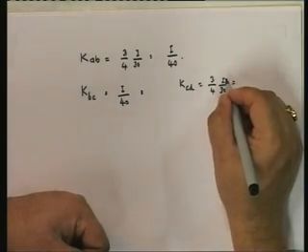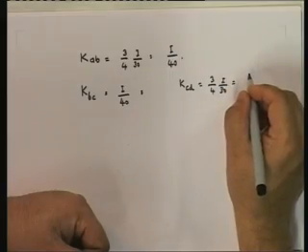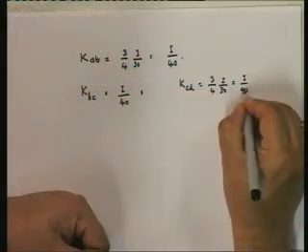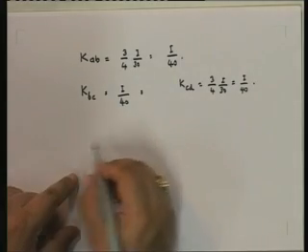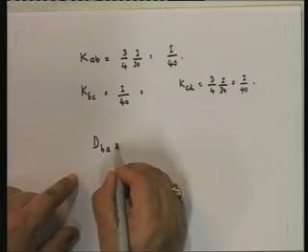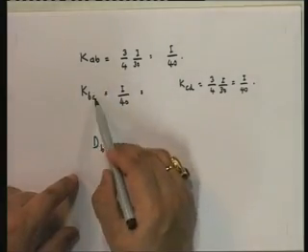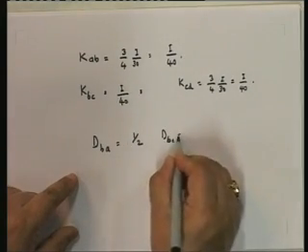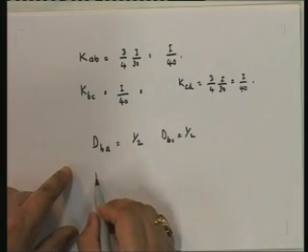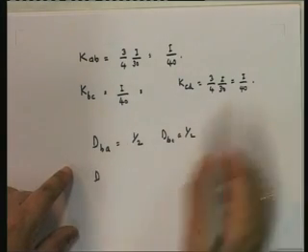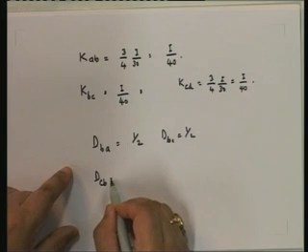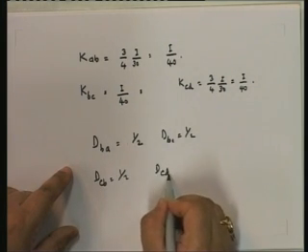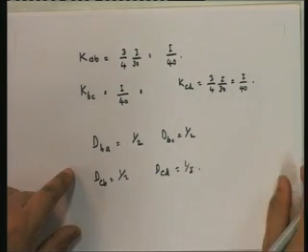C is going to be the continuous, fixed end, D is going to be the roller. In AB, A is going to be the hinged end and B is going to be the roller. So distribution factor DBA is going to be KBA plus KBC upon the summation, which is going to be half. DBC is going to be half, and at C it's going to be I upon 40, I upon 40. So DCB is going to be half and DCD is going to be half.